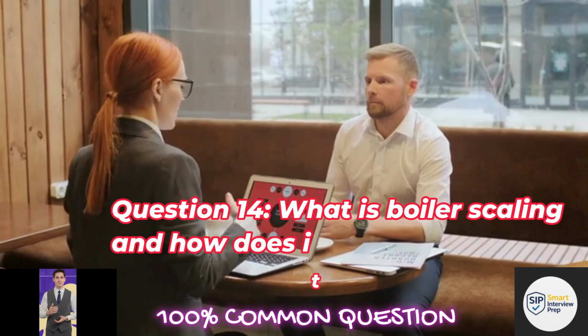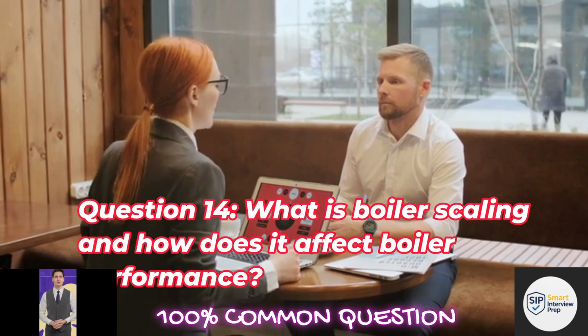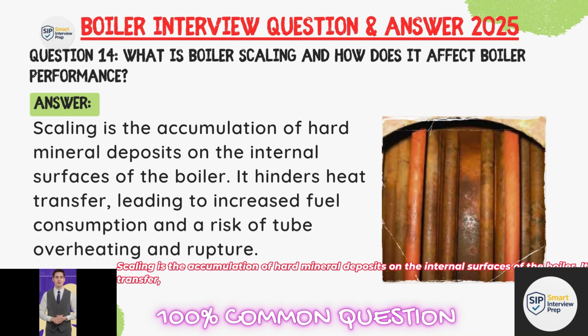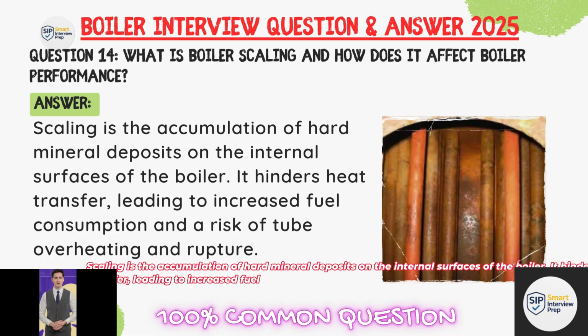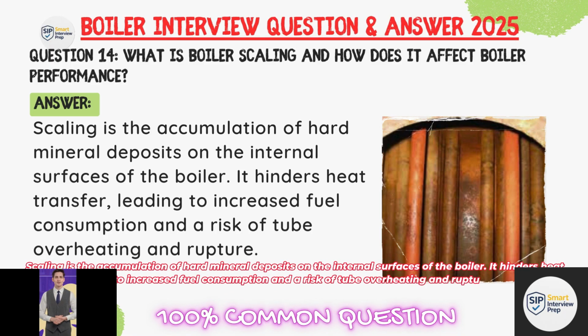Question: What is boiler scaling and how does it affect boiler performance? Answer: Scaling is the accumulation of hard mineral deposits on the internal surface of the boiler. It hinders heat transfer, leading to increased fuel consumption and a risk of tube overheating and rupture.